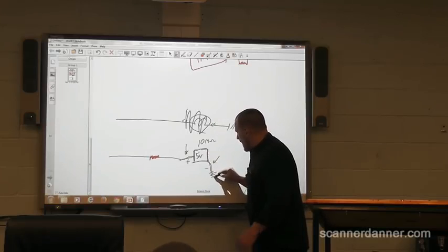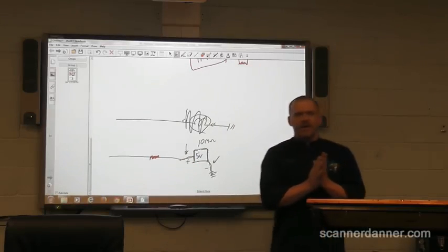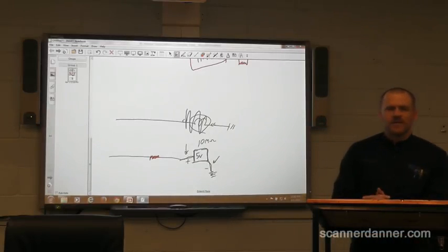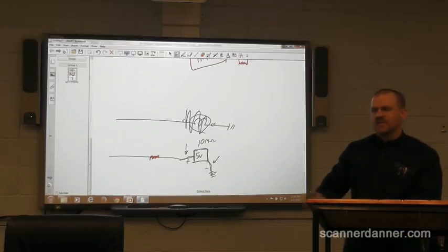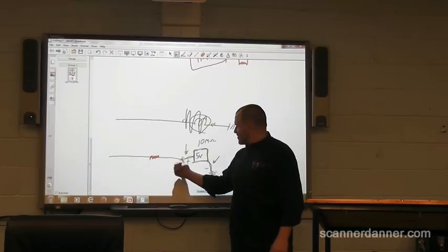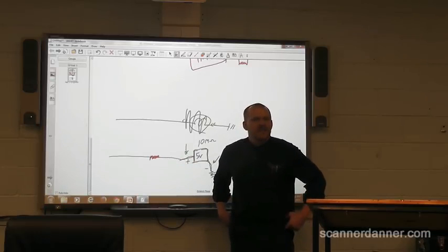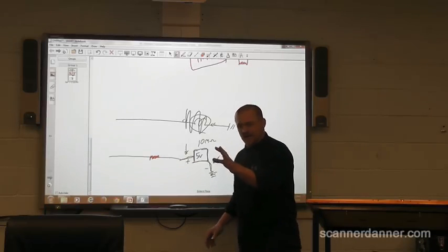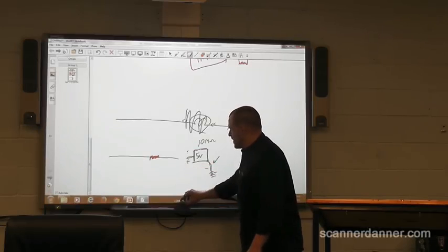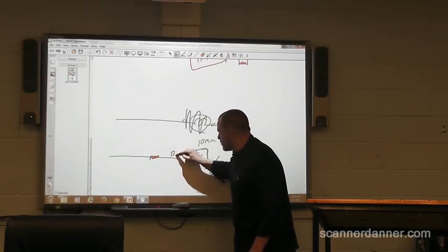Going to ground. Why? How can we justify that? That contradicts what I told you yesterday. It doesn't. Your meter's the path. And that resistance over here is so bad that your voltmeter is reading a lower voltage because the meter itself is causing it. If I could disconnect my meter and have x-ray vision and look into that wire right there, I promise you it would be 12 volts.